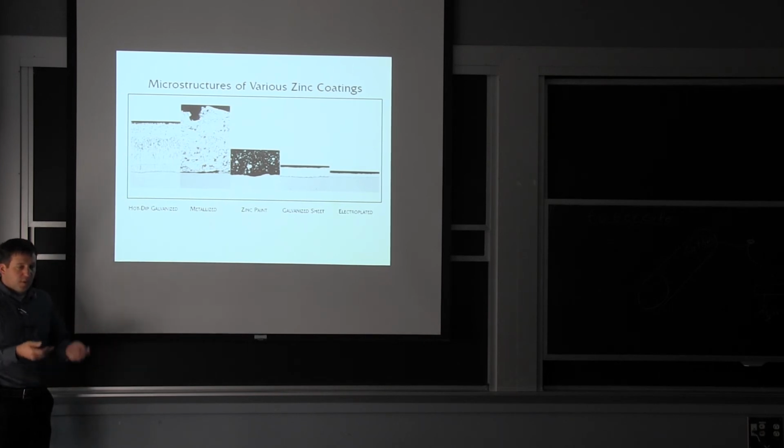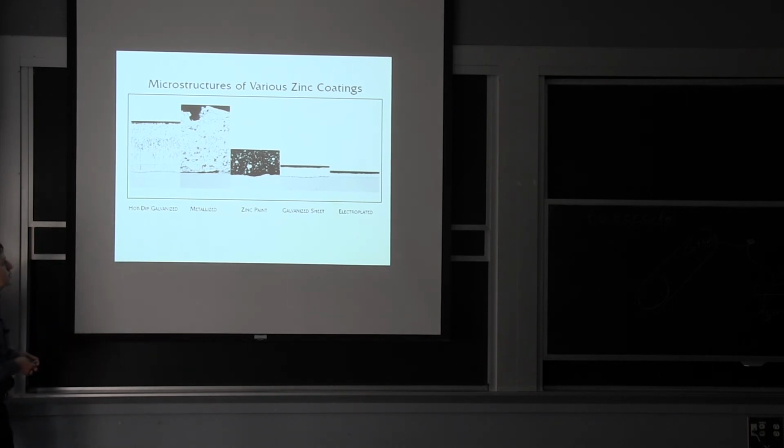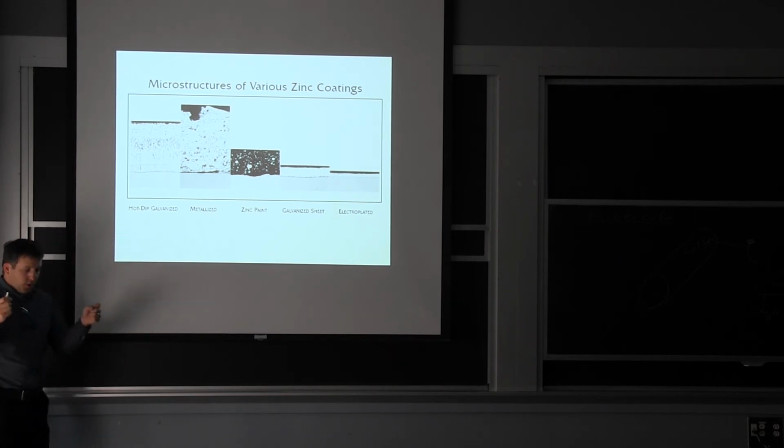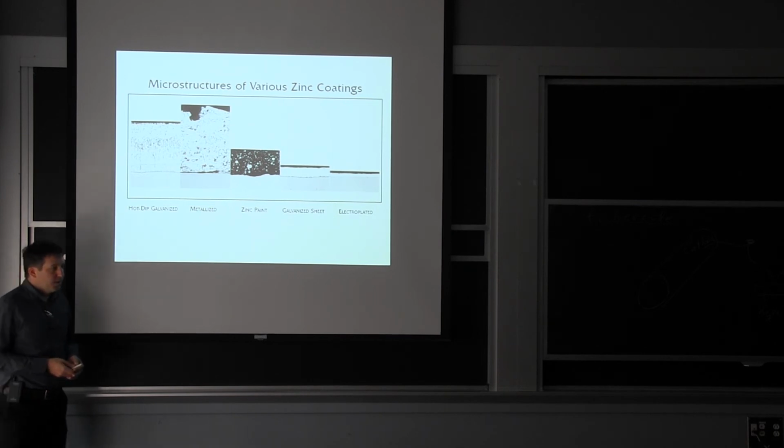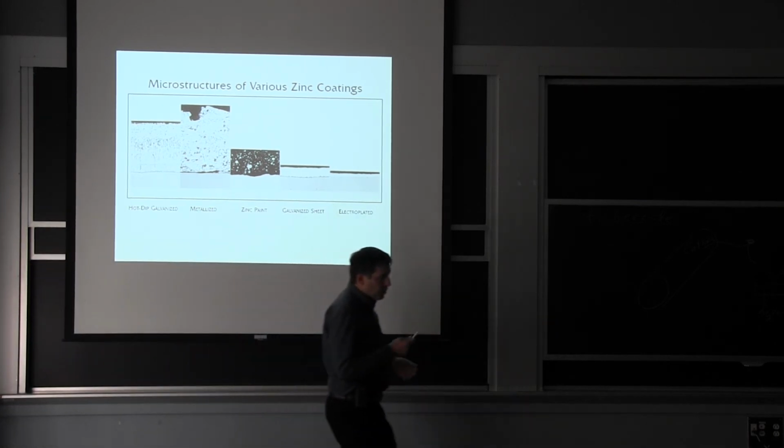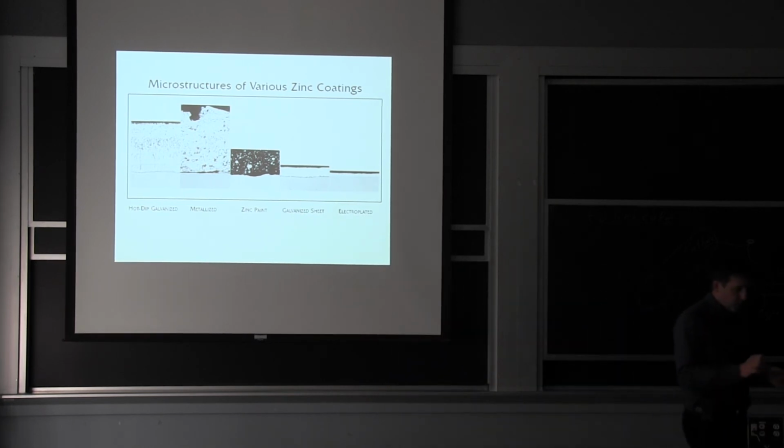And you have to be careful what the temperature of the zinc is, to not create trouble for the steel. But if you control your temperature, you dip it for a certain amount of time, you make a relatively thick casting of zinc on the surface. And the way you can confirm that it's hot dip galvanized is when you see the individual grains, the big grains on the surface. So if we look here, a Stata Center, or even just a light fixture post outside, a lot of times it has been hot dip galvanized.